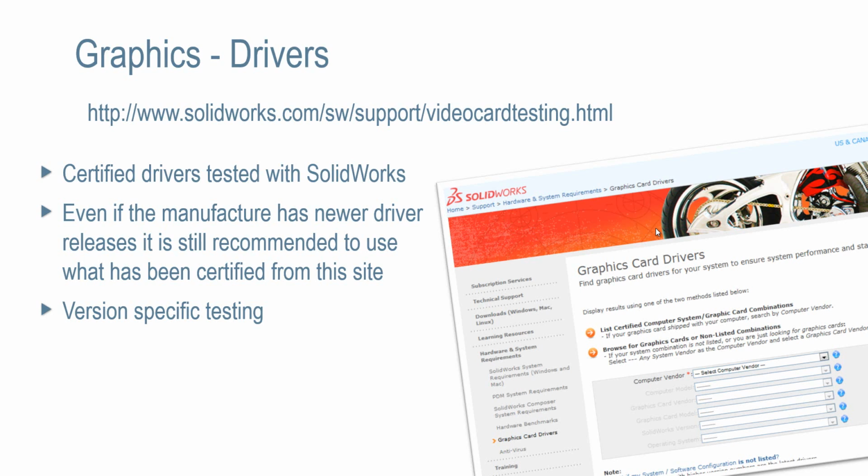People forget that service packs are linked to drivers, not releases. So if you're on 2014 service pack 0 and you install the right driver for service pack 0, when you upgrade to service pack 1, you may find that the driver that's been aligned with it is not the one you're currently on. So my recommendation is to at least every couple of months just check, using either this screen or the RX tool, whether your driver is in date.